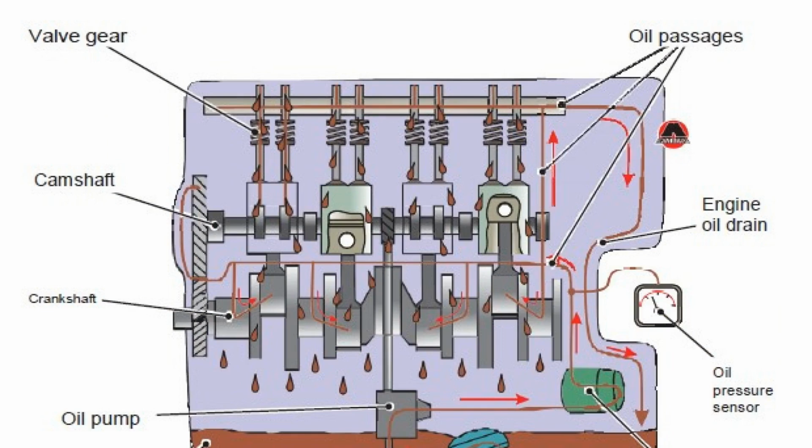Structurally, wet crankcase lubrication systems consist of the following components: oil pan, oil pump, oil intake device, pressure reducing valve, oil lines, fine and coarse filters, radiator, lubricant level and pressure sensors, oil filler neck. When the power unit is running, the oil pump injects pressurized fluid through the oil intake screen into the filter, from where it is directed to the central oil line located in the cylinder block. From here, under pressure through the channels in the block partitions, oil enters the crankshaft, lubricating first the main bearings, and then the connecting rod bearings.